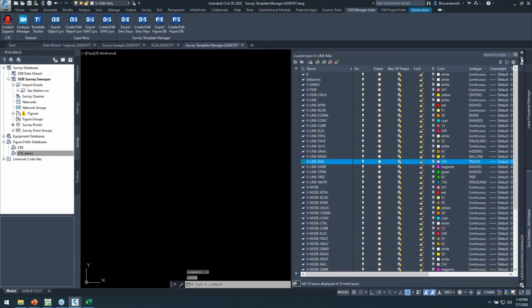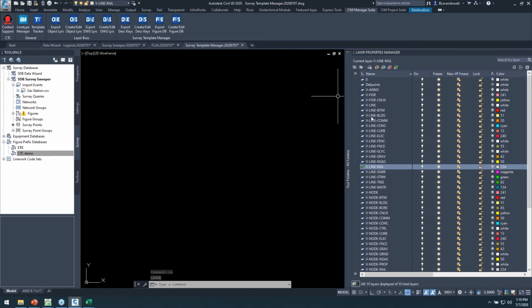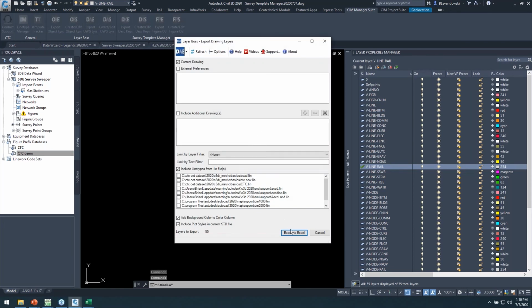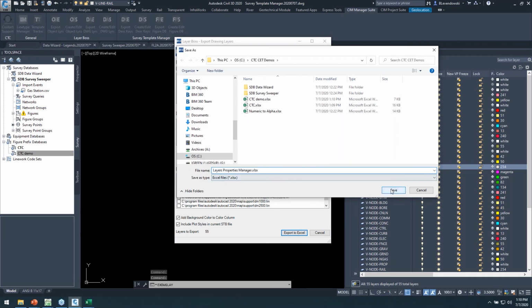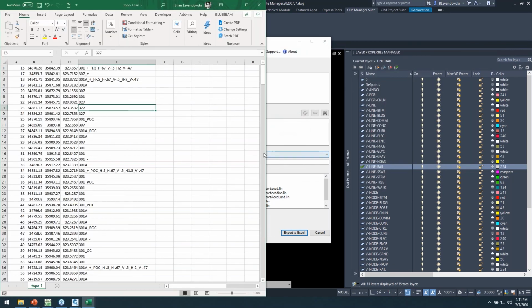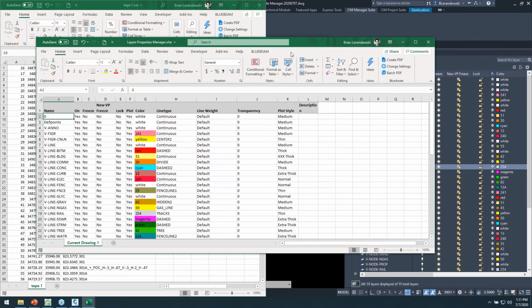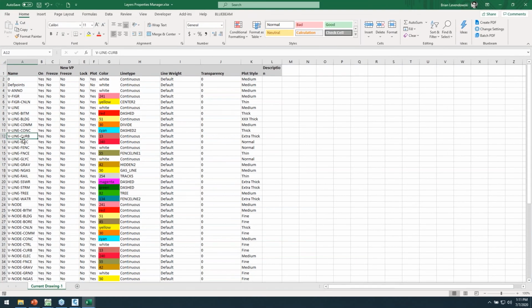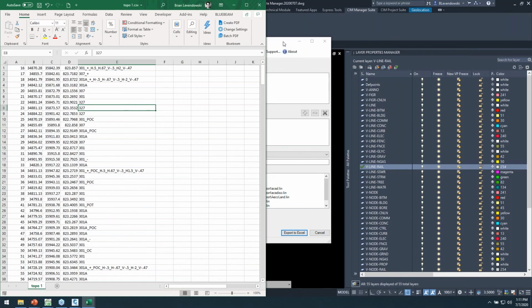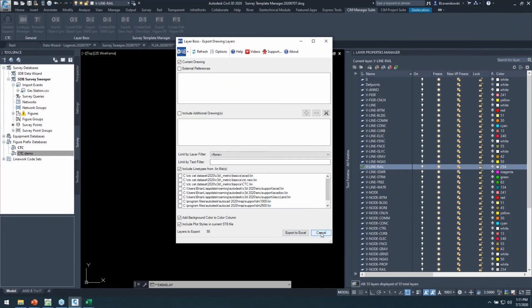And then one other tool set I'll just mention briefly here because it applies to all Civil 3D users. What about the layer dialog itself, right? We can export that entire thing to Excel. And I tell it to open it right away. And I can work with my entire layer manager in Excel, make any changes, additions I want, and then sync it back to Civil 3D, okay?